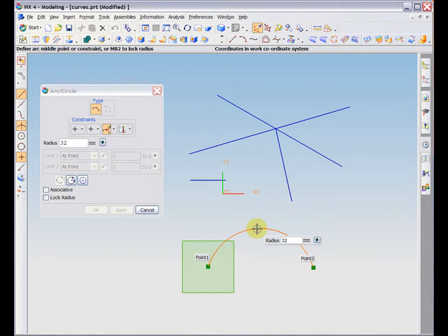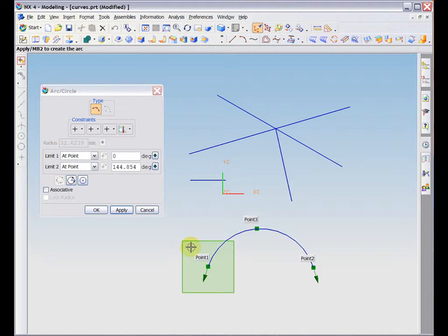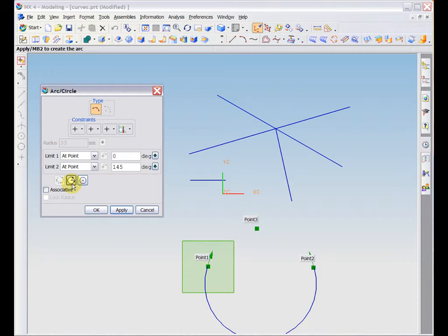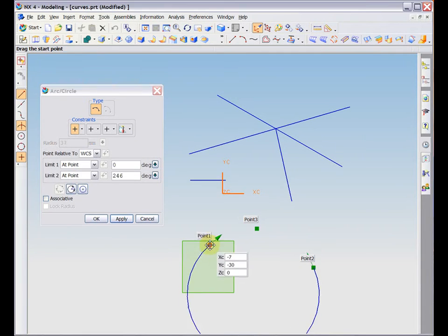After choosing all 3 points, you may also change your arc by using a few commands in the dialog box. One example is the Complementary Solutions option, which will return the complement of the displayed arc. Another option is to choose to make the arc a full circle. As in the line, you can also just grab the handles and drag the endpoints or radius with your mouse.